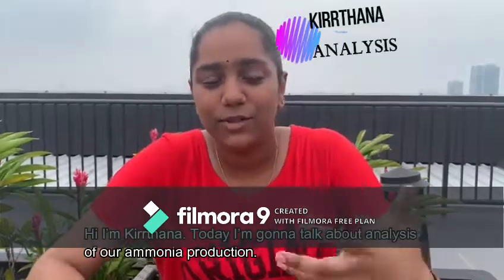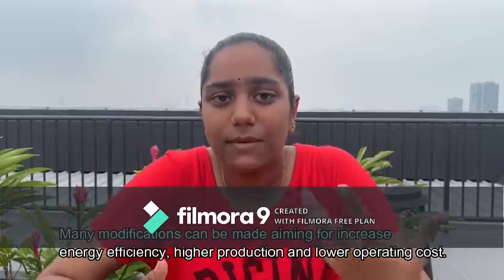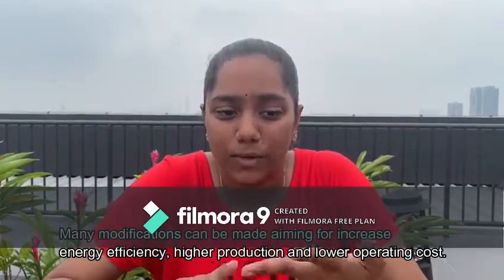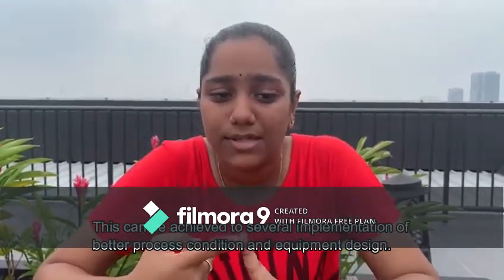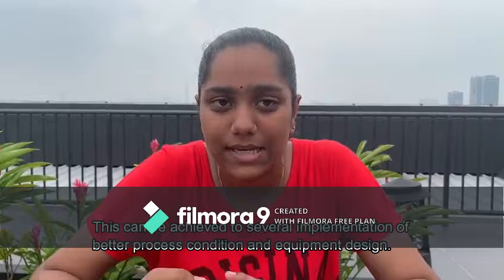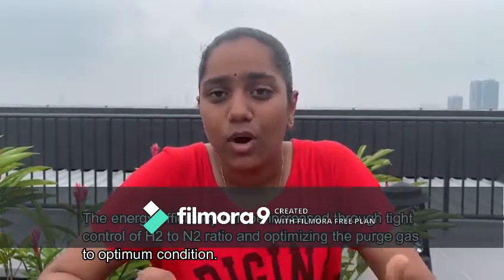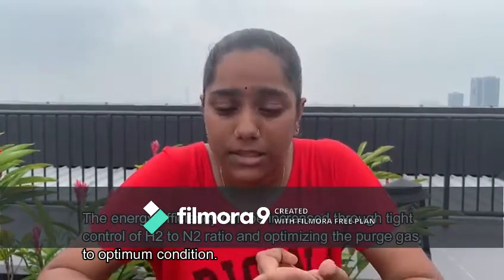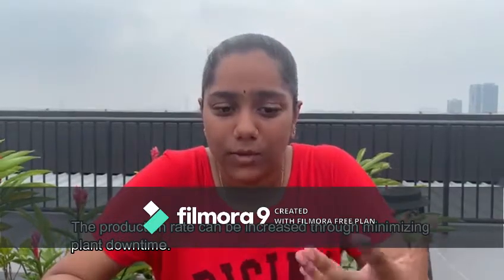Hi, I'm Kitana. Today I'm going to talk about analysis of our ammonia production. Many modifications can be made aiming for increased energy efficiency, higher production and lower operating costs. These can be achieved through implementation of better process conditions and equipment design. The energy efficiency can be increased through tight control of the H2 to N2 ratio and optimizing the purge gas to optimum conditions. The production rate can be increased through minimizing plant downtimes.